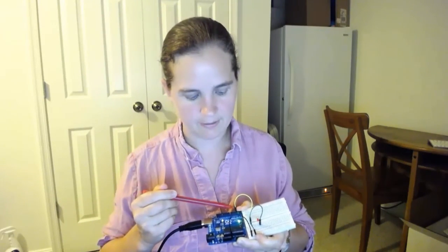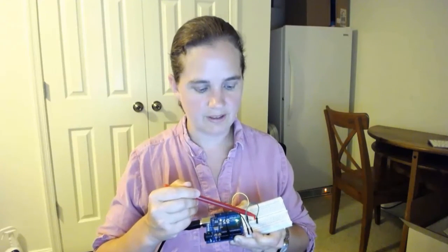So in this case, I uploaded to this Arduino here, and what I can see is I've set up the Arduino such that I have a wire connecting my pin to a current limiting resistor. I have the other side of that current limiting resistor connected to the LED, and the other side of the LED connected back to ground, which is how I should have things set up, but my LED isn't on.